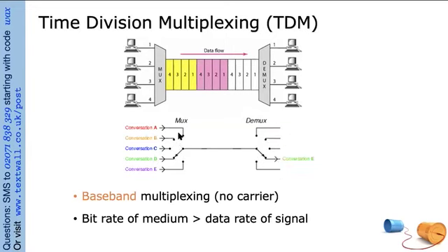So you can't have different sample rates for different conversations. As you can see, it's the same clock. In more advanced TDM systems, you can have more than one slot per frame for a high frequency message like E. Instead of having 1, 2, 3, 4, you could have 4, 3, 4, 2, 1, 4, 3, 4, 2, 1.